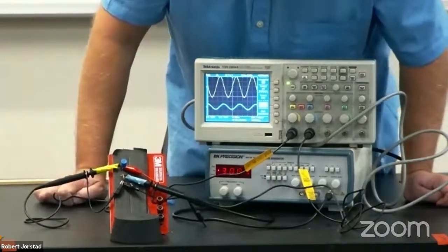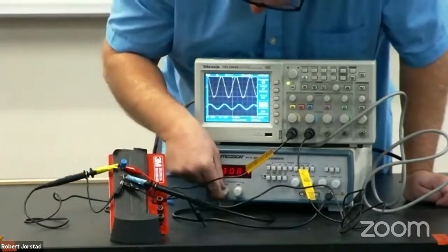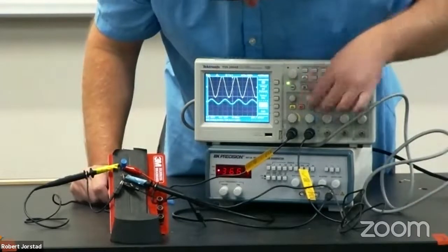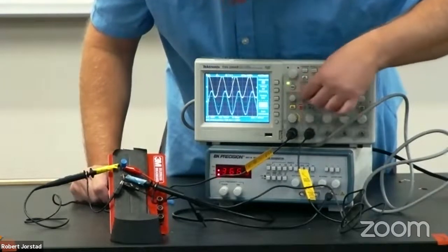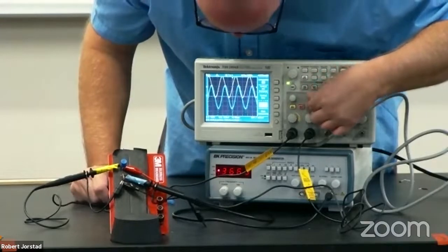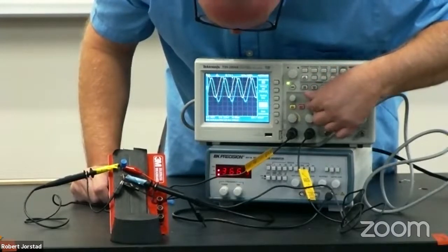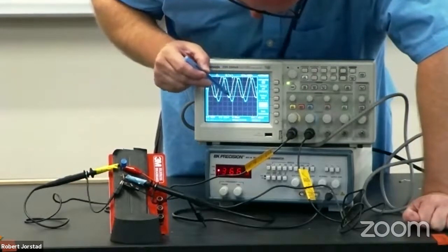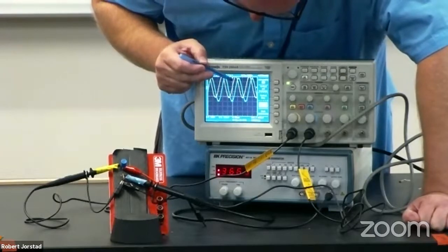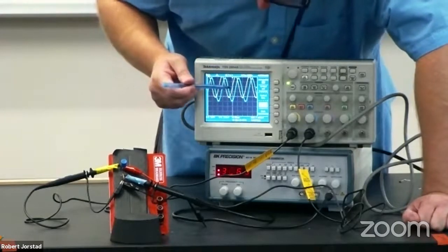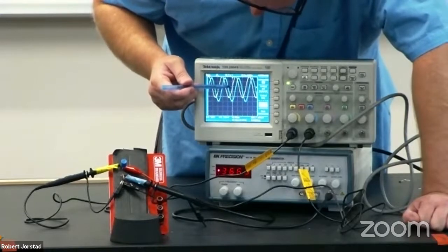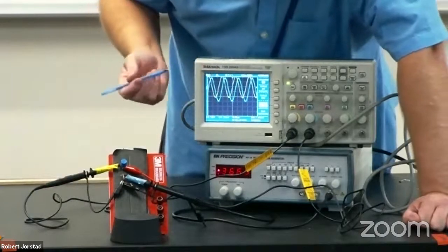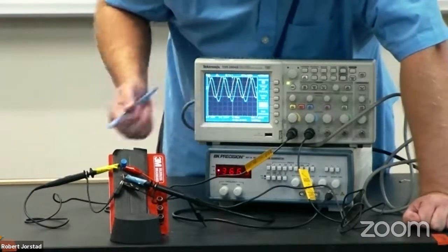So now what's going to happen here as I change the frequency? Or actually, let's do this. I'm not changing these voltages. I'm just changing where they're displayed. Here I'm just changing the units, but I want to point out they no longer peak at the same time. In fact, I see that the yellow curve or the upper curve is peaking before the lower curve. So that means the voltage is peaking before the current. We would say the voltage leads the current, or you could also say the current lags the voltage.